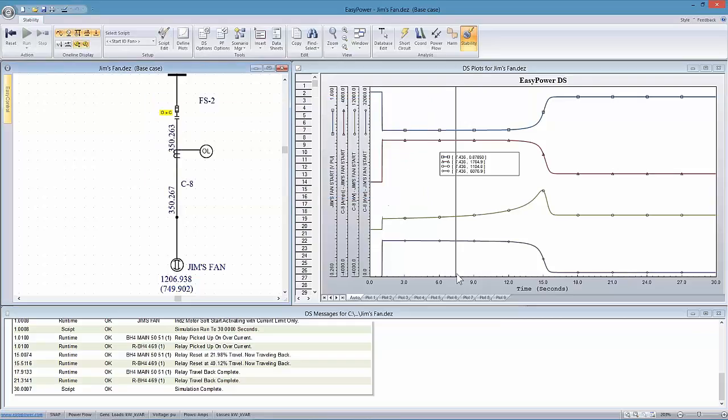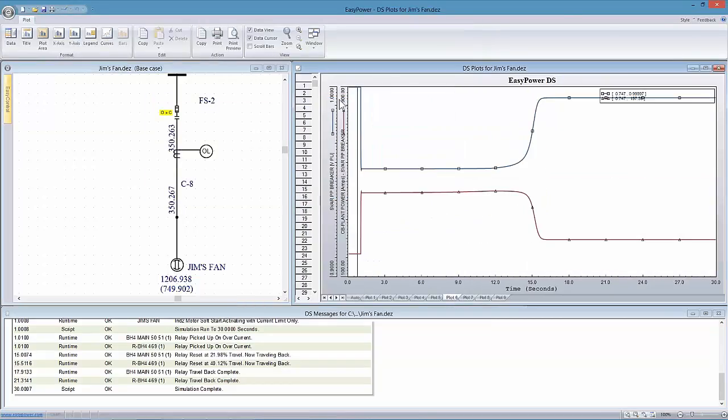So as I go to look at plot 6, I can see now my current goes from 197 amps to over 450 amps, and it maintains that for about 14 to 15 seconds. So during this time, because this is very close to the set point of the breaker for the whole plant, the overload relay, I'm at risk of bringing down the whole system.